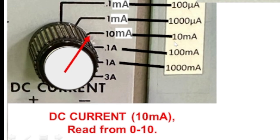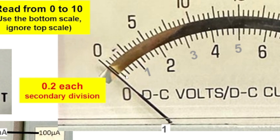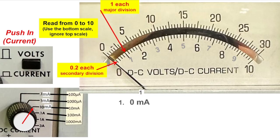Now, each of the secondary divisions, the small lines here at the bottom, represents 0.2, and the longer lines at the bottom represent 1 each. Therefore, this is 2, this will be 3, and so on until you reach 10.